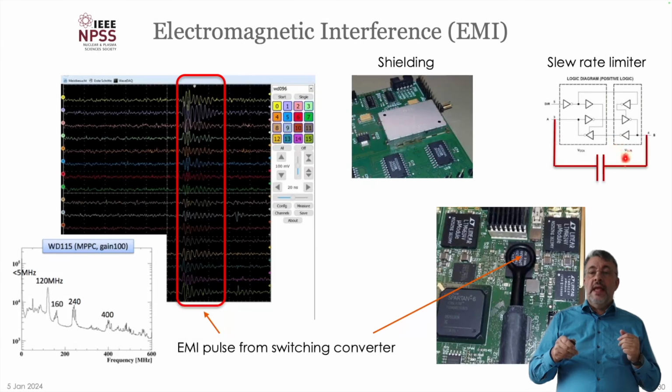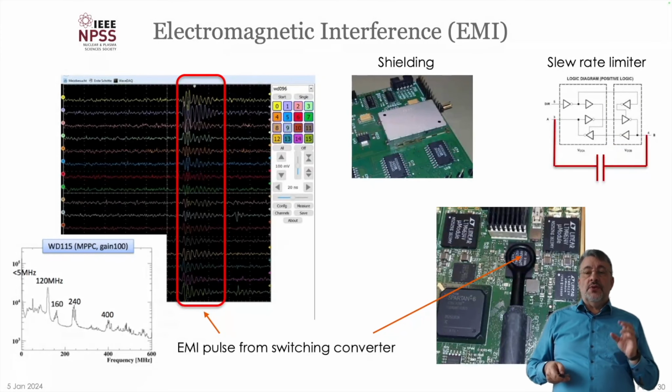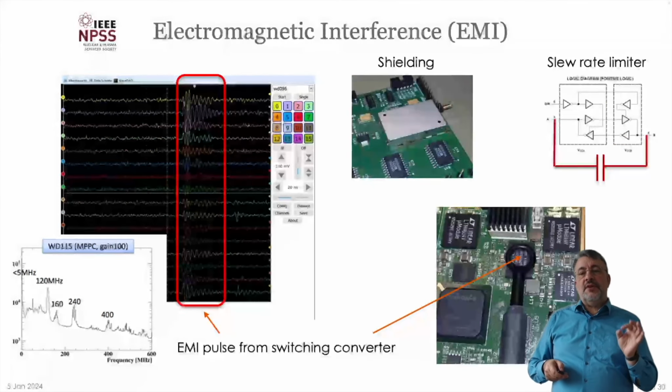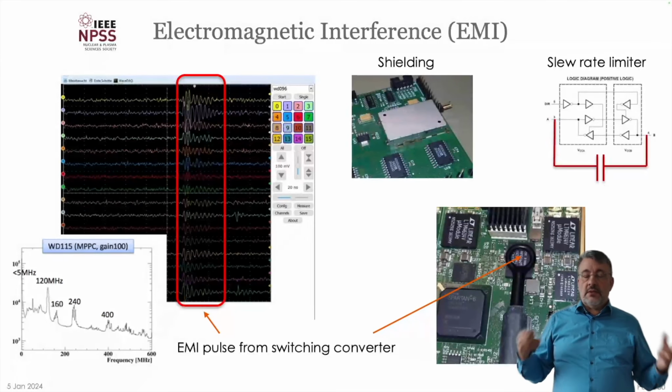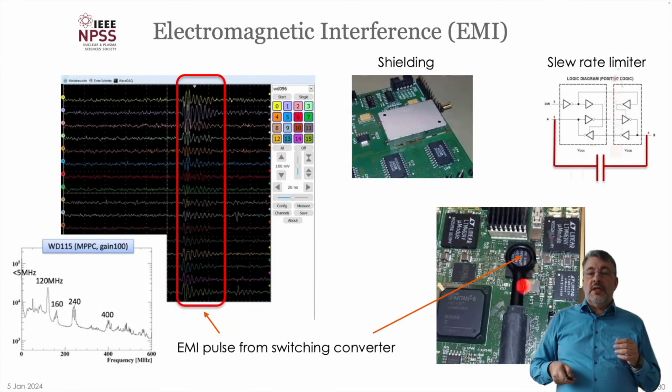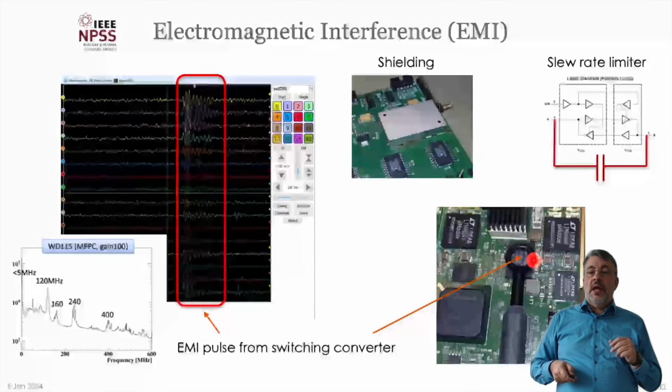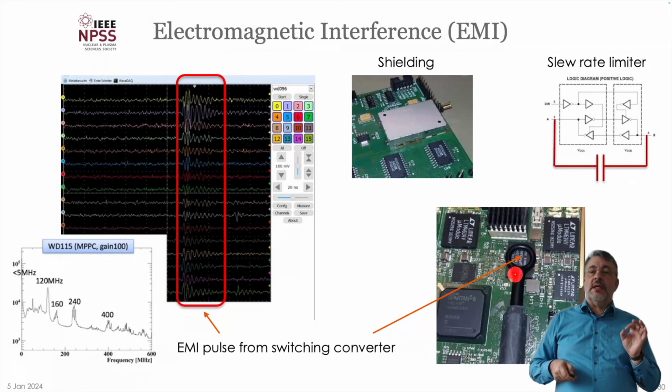dramatically. Another very important thing is that you carefully have to check every digital chip in your design and measure how much EMI it produces. This usually is not written in the data sheet, you have to measure it yourself. And it's not obvious which are good and which are not, so you have to measure lots of them. We actually use an oscilloscope probe with a little magnetic sensor, which we put on every chip and measure, and only hand select those chips which produce the least EMI and only put those on our electronics.